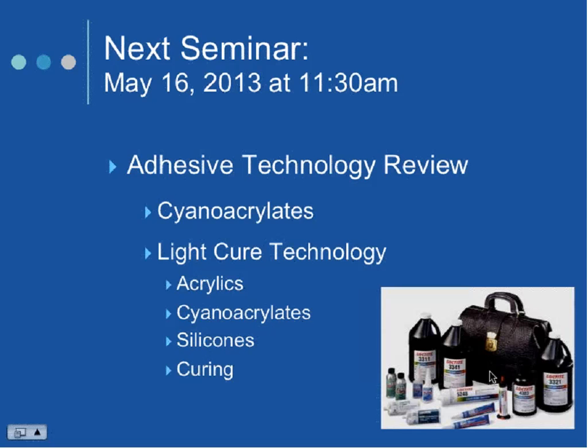I've seen customers that are bonding with our cyanoacrylate do a phenomenal job of cleaning. They clean the parts, now they're going to dry them for 20 minutes, and they're going to immediately bond them, and our adhesives don't work. The reason is they've driven off all the moisture, which is the trigger that makes cyanoacrylates work. So you can go almost too far. We need some surface moisture on there. You need to let it reacclimate to the relative humidity in the room if you're working with cyanoacrylates. It's not usually a problem with the other adhesives.